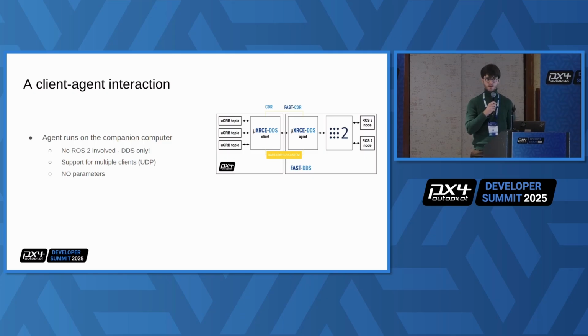The agent runs on the companion computer. It connects to PX4 through serial or UDP. It supports multiple clients, either multi-serial or UDP: one agent, multiple clients connecting to it. This is very useful for running multi-vehicle simulation, of course.